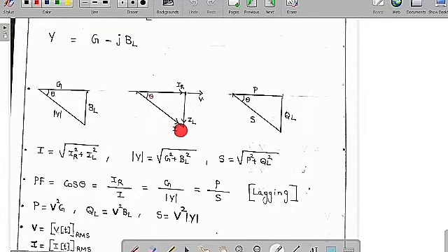So always you can see clearly the current is going to lag the supply voltage. So we can say it is a lagging power factor. No matter whether you connect the resistor and inductor in series or in parallel, it is always a lagging power factor. Means we can say simply the current is going to lag the supply voltage.